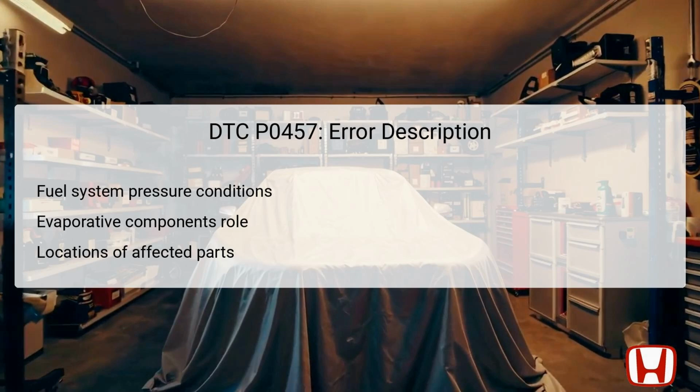The components involved include the fuel fill cap and its sealing mechanism, which should be tightly secured and free from damage. You can locate the fuel fill cap on the outside of the fuel filler neck, which is connected to the main fuel tank. Additionally, the EVAP canister works to capture fuel vapors, but an improper seal can disrupt its functionality. It is important to check these components, not just for integrity, but also for correct installation to prevent future leaks and ensure proper system pressure and vacuum.